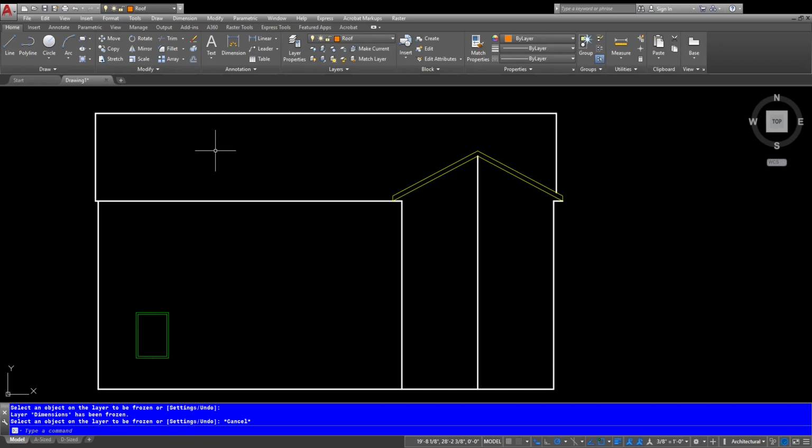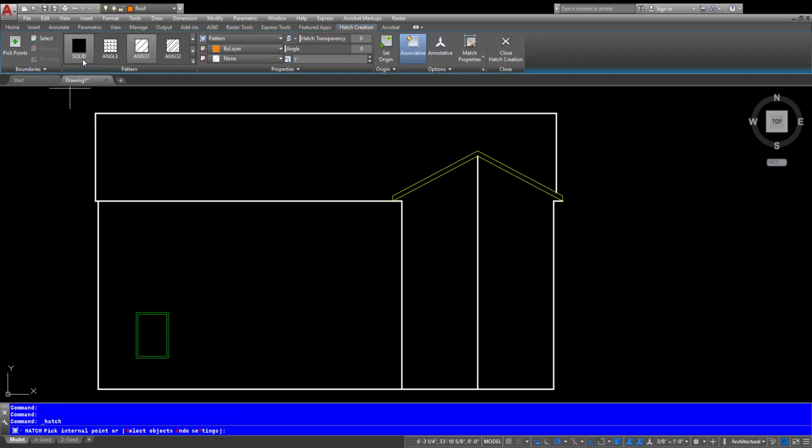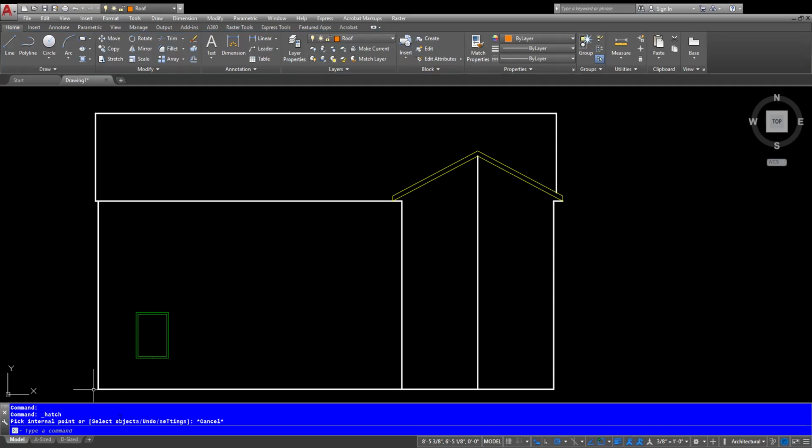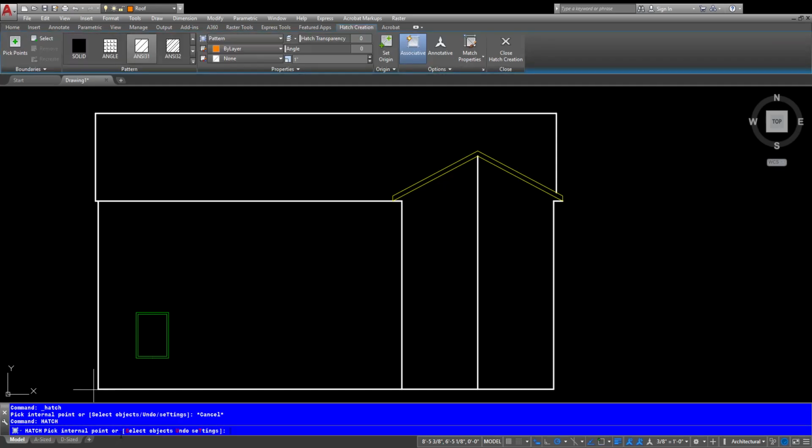And if you take a look, the roofing, if we go to hatching, the hatching tool is actually right up here, but you can't really see that. If you click on this right here where my cursor is, it'll bring up the hatching. Other than that, you just type in the word hatch by going down here and typing in hatch, H-A-T-C-H, and they both do the same thing. They bring up a dialog box.